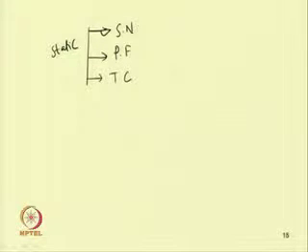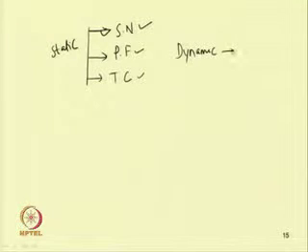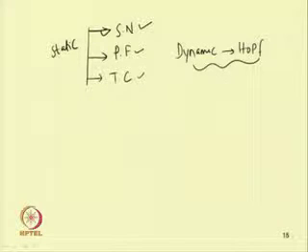In case of the dynamic bifurcation, we have Hopf bifurcation. In this static and dynamic bifurcation of the fixed point response, we know that saddle node bifurcation and Hopf bifurcation only are the generic bifurcations which will not change by changing the control space.